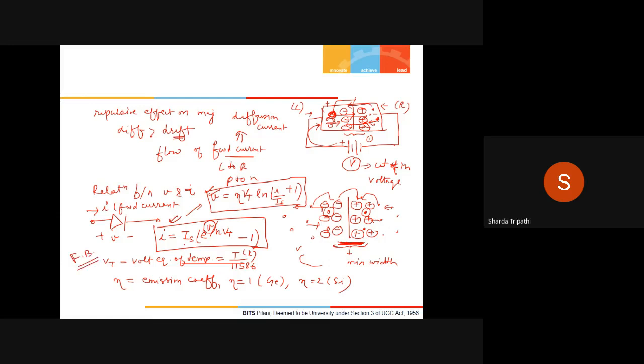In the reverse bias region, we do have a small current, that is my reverse saturation current, but this is actually the property of the material itself. You cannot find that by using any formula. Of course, you can find that by this formula given some forward current, but otherwise Is is actually the property of that particular material. For example, for germanium, this is on the order of microamperes, while for silicon, this is on the order of nanoamperes.